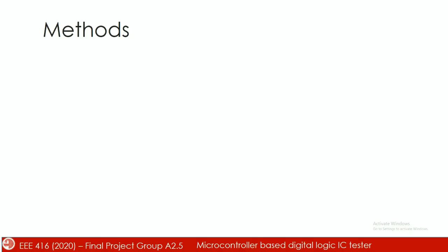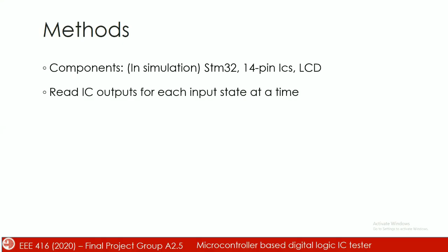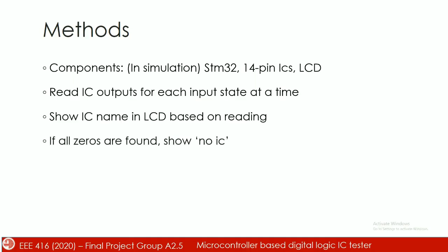I'm going to be talking about the methods that we followed during our project. The components that we utilize are STM32, a 14-pin IC or ICs, and an LCD. During the simulation, we read the IC outputs during each state of the input provided by the STM, and the readings based off the outputs are evaluated by the STM32, and based on that, the LCD shows the IC name.